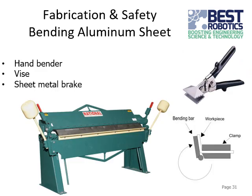Sometimes you may want to bend pieces of aluminum. They have special bending tools. You can use the sheet metal brake, the big thing shown here. That gives you a nice edge to bend along, and it can help you with the bend. They have hand bending pieces, but a vise can also work really well for that.